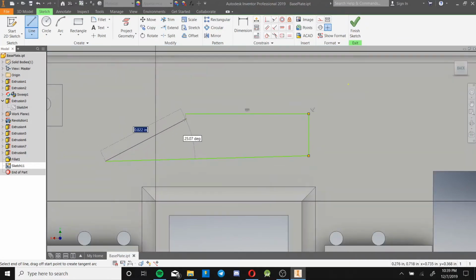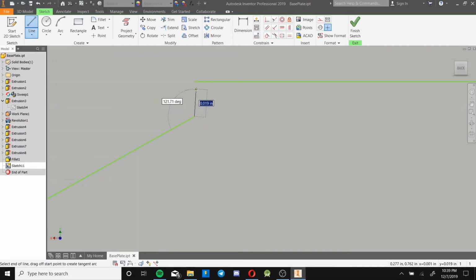Just a note here that if you're clicking onto a point, you have to make sure that the dot, you see on my cursor how it's green, that means you're clicking the point. If it's yellow, like here, that means you're not clicking the point. And if you click it and you zoom in, it's not actually on that point.